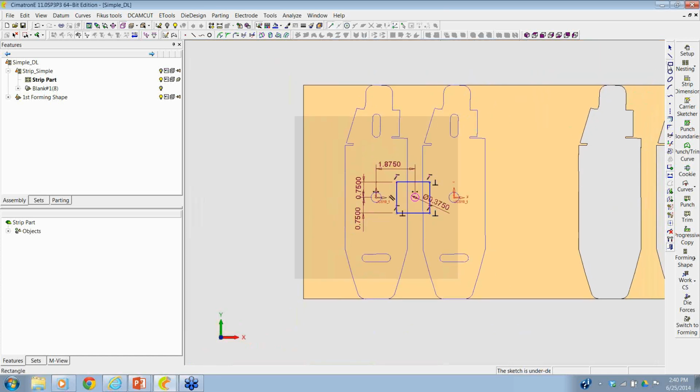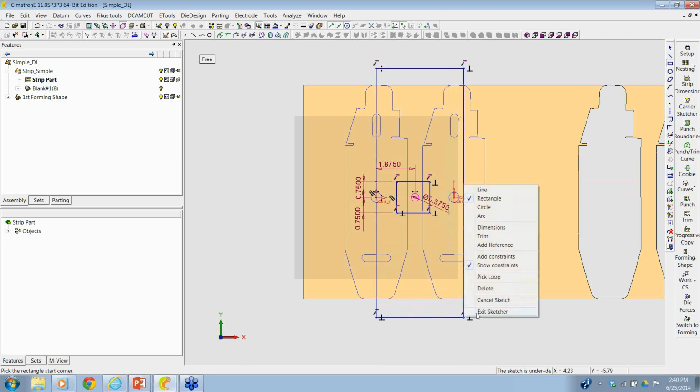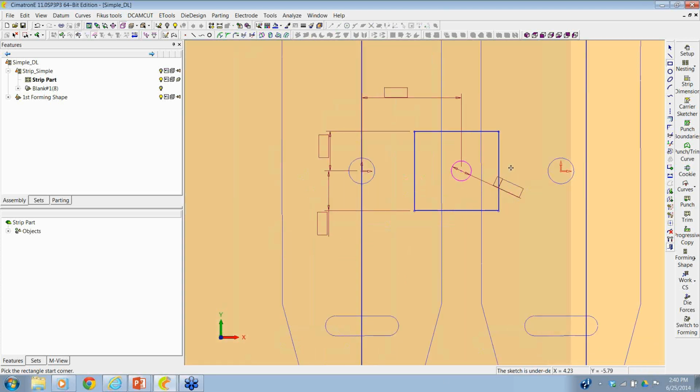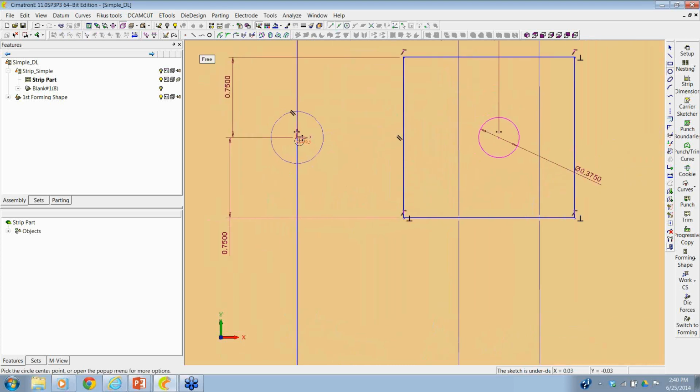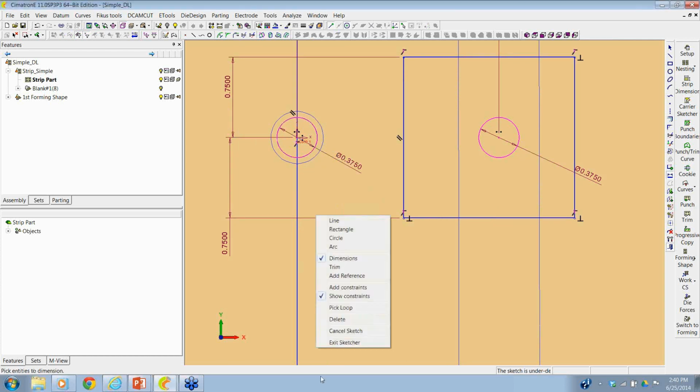And then also, let's capture about where my punches are going to go. I have 2 punches that would extend out into the stock guide area, and I'm just going to eyeball those in for now. So, one more thing I would like to do, since I've got this shape here, is drop a punch in there first before I roll the edge up. Okay.